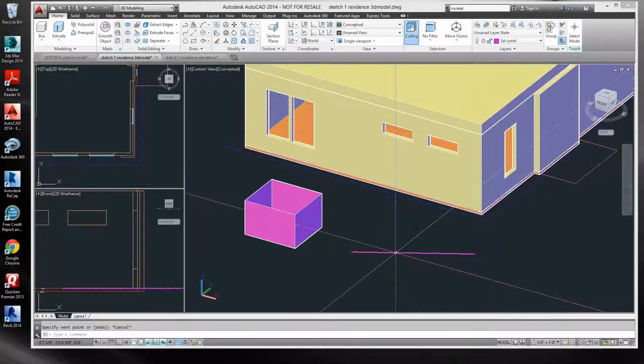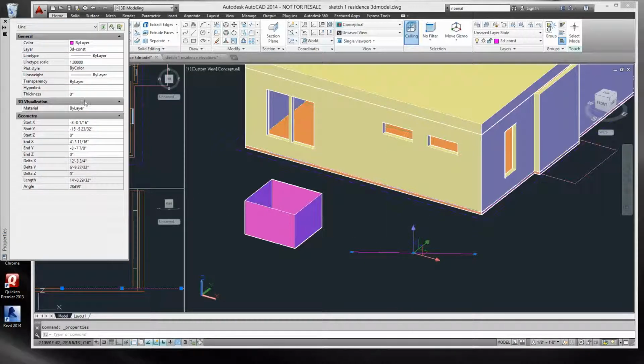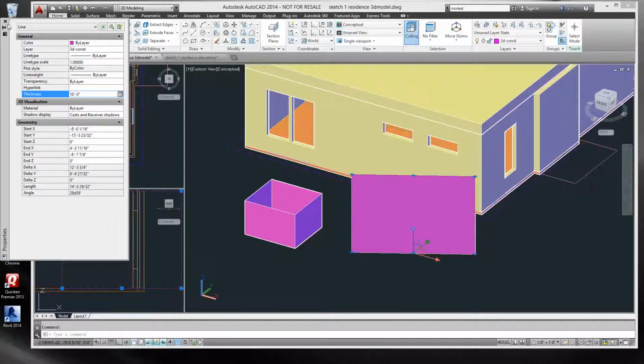Now what we have to think about a surface is that it has no depth at all. I want to use the word thickness, but notice if I grab that line, go to the properties command, and I actually change the thickness in CAD to 10 feet, I now have a 10-foot tall line. We just have to understand that thickness is how we actually extrude lines, in a sense. It's not really an extrusion of that line. We have converted that line into a surface.